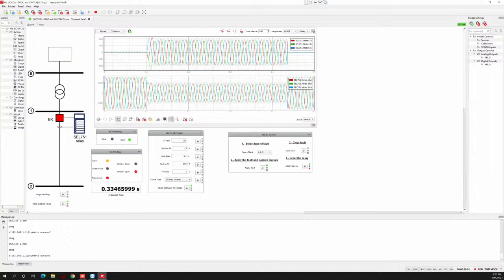And that curve, that is current versus time, is basically defined so that for small currents, the relay takes more time to clear the fault, and if the current is extremely high, the relay will take less time to open the circuit breaker, okay? That is the reason we call that inverse time, because as the current is high, the time is reduced, okay? And that is what she's planning to do now. She's planning to test one inverse time overcurrent protection. Okay, do it.